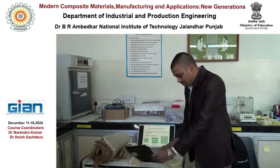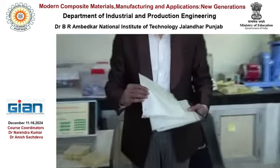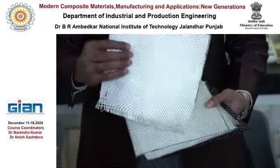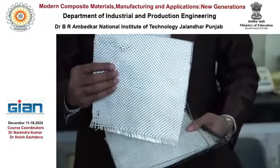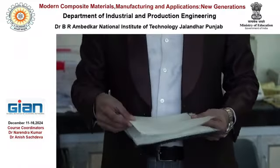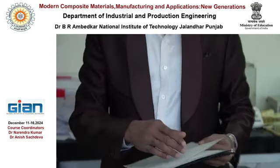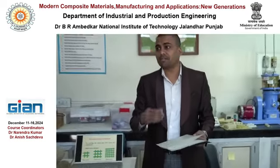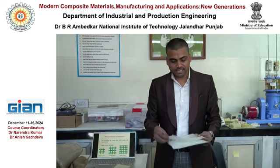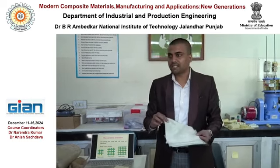For example, as I showed you yesterday, this is the glass fabric preform. This is a two-dimensional fabric because it has only length and width dimensions, and of course it has a certain thickness, but this thickness is, in comparison to the length and width, very, very small, and the maximum thickness is just 2 times the constituent yarn thickness, right?